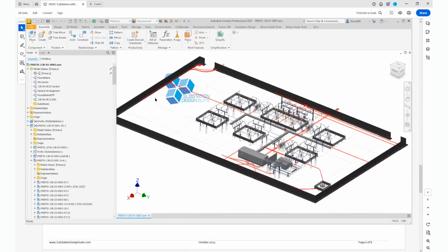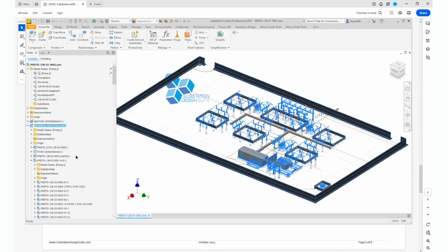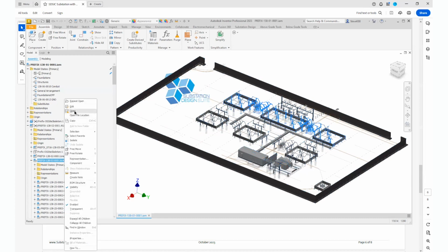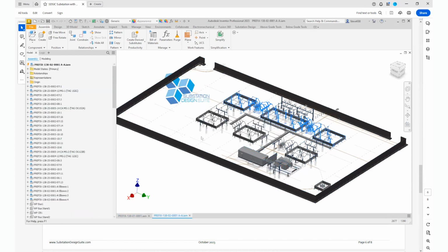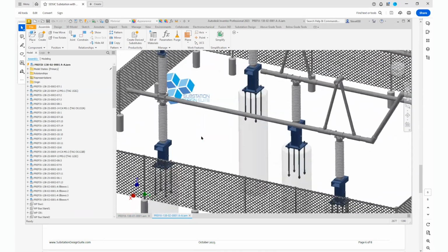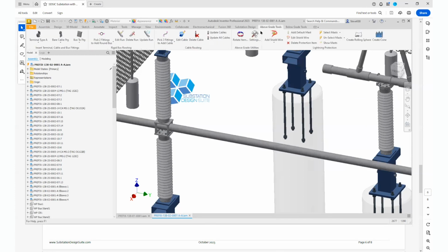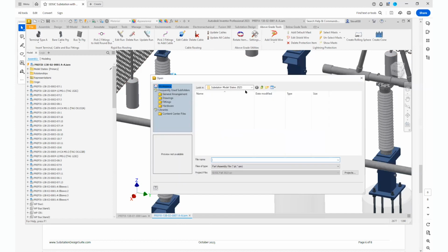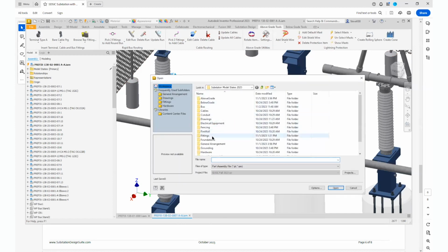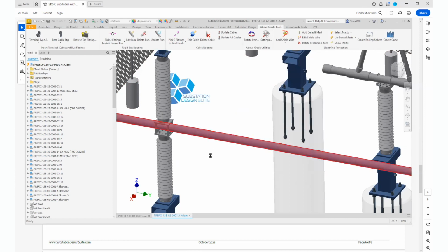There she goes. Okay, I want to open up this. I want to make sure we understand what I'm saying with positional rep one. So this is above grade. Here's this guy here. Let's open this guy up. If you ever read some of my documents, I talk about combining assemblies so that you can do different things. So I'm going to look at this piece of pipe, and I'm going to put in my above grade tools. I'm going to browse to fitting. Okay, come down my fittings. Okay, Josh, cross your fingers. We're going to put this guy in. I'm going to put it on that pipe.